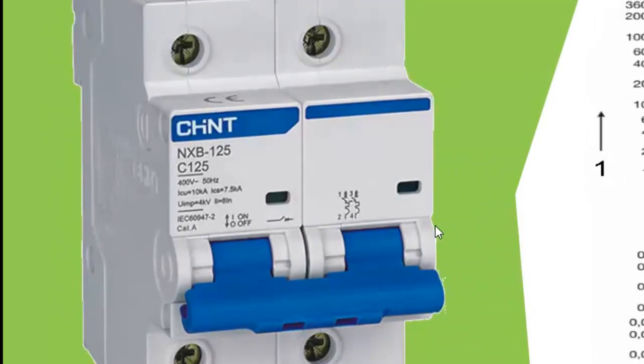If you look to the left, this is a circuit breaker, and what you have here is the rated current, 125 amps. The C, before the rated current, tells us clearly the curve that is guiding the operation of this circuit breaker.